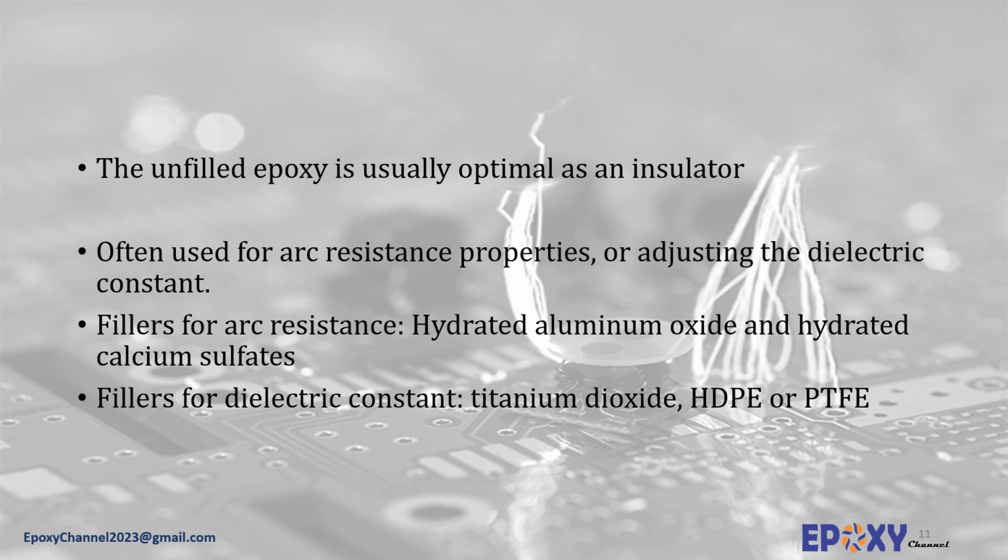Highly hydrated aluminum oxide and hydrated calcium sulfate will improve arc resistance if cure temperature is sufficiently low to prevent dehydration of the filler particles. Mineral fillers generally result in increased dielectric constant and dissipation or loss factor. Some mineral fillers, such as titanium oxide, have been reported to lower the dissipation factor of the epoxy systems.